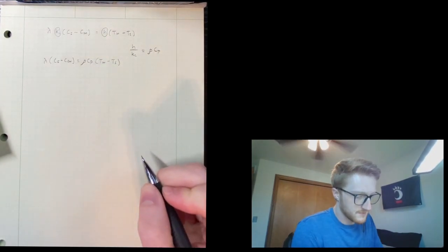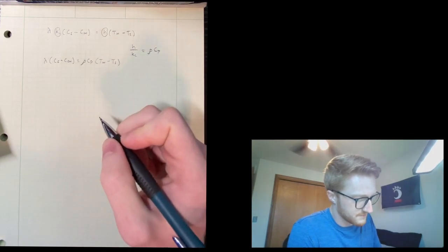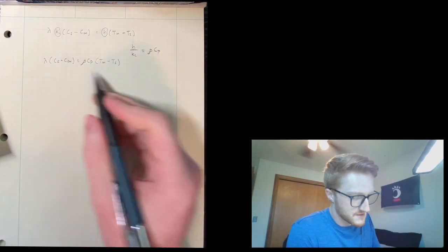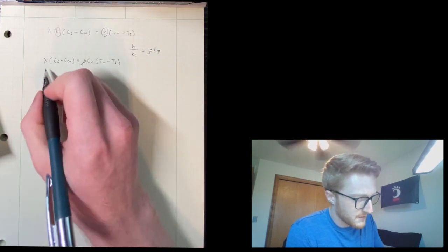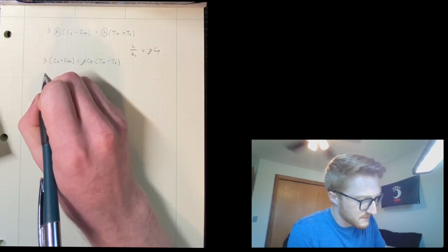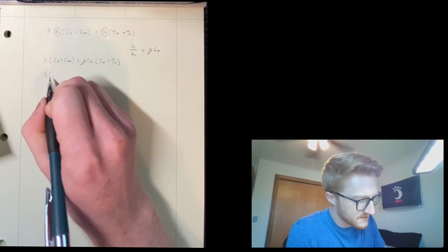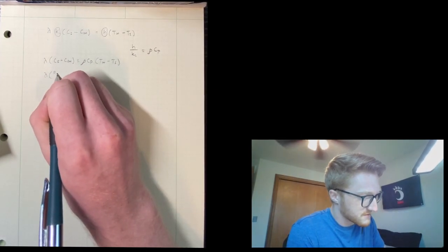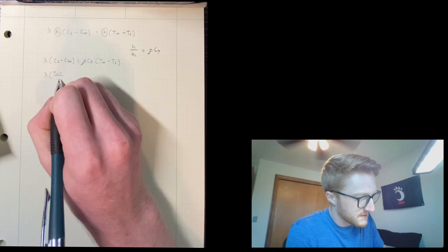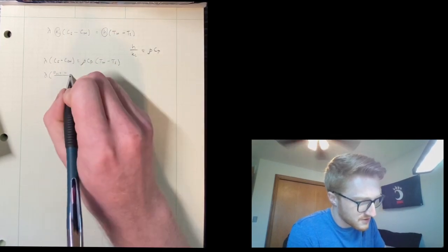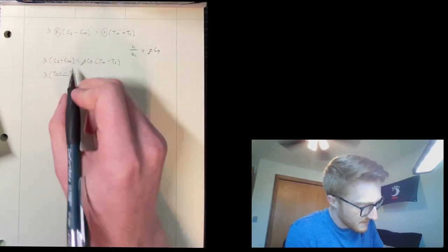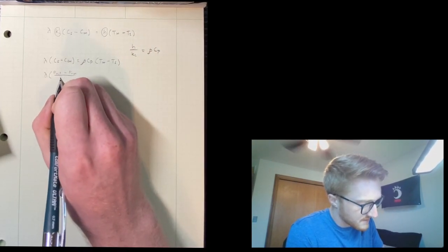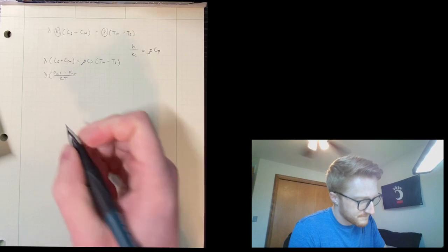And so from this, we can rewrite the concentrations as partial pressures divided by the gas constant times the temperature. So we can write that as the partial pressure of the water at the surface minus the partial pressure of the water in the air, divided by the gas constant times temperature.